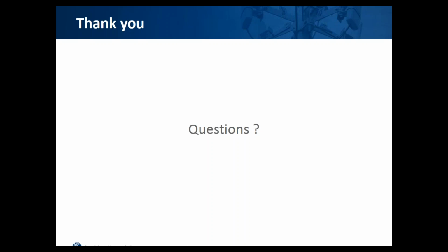That's a good question, and it depends on the size of the packet, and we have different versions. You have the 2.5 millisecond frame size and the 5 millisecond frame size. If you have the 2.5, you have more packets, but the overhead becomes much more versus the 5 millisecond packet size. But overall, this is not the PHY rate, but the bit rate that is included, which is the 300 plus Mbps.